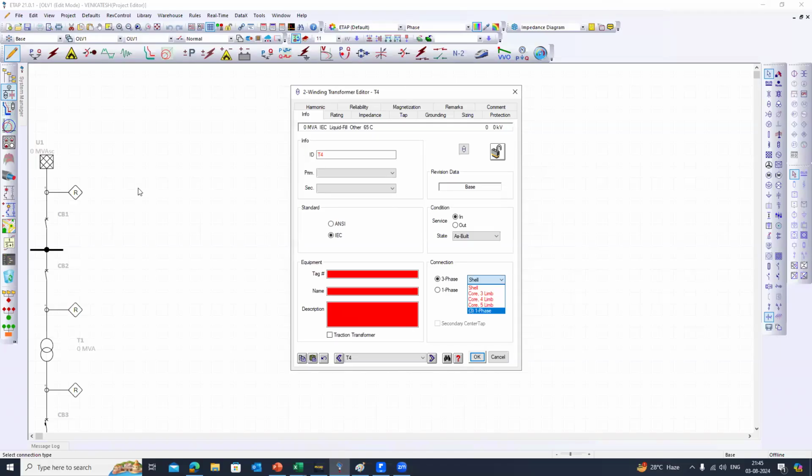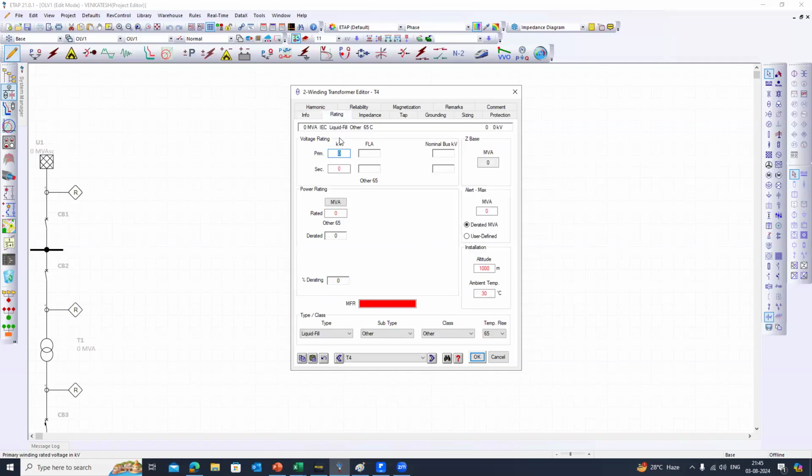Next coming to the rating phase here. So here if you see, sir, how the redundancy is maintained in the single phase? You are having three different transformers on different phases, right? Suppose if any transformer fails, you can replace it with the spare transformer.